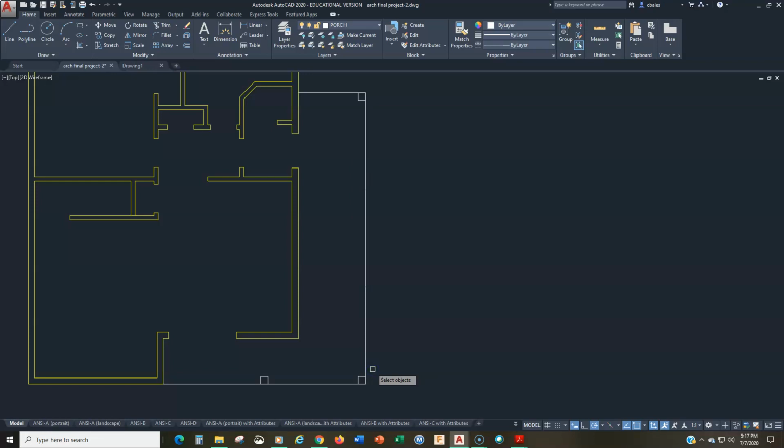But watch, I hit enter, and then I'm going to move off of this, and can you see that? It's very light. I'm going to move straight off. There's one point and another point. So now what do I do with it? These points are positioned exactly where the midpoint of the column should be. Now how do we grab a point? This is a new object snap that we haven't used before, and that is the node object snap. I actually have it turned on, node, and that's how we grab this point.